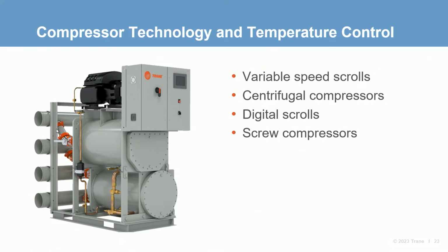As shown on this slide, a centrifugal compressor designed with an integral drive could be a great choice. Same benefits of modular, very efficient, oil-free, and offered with shell and tube heat exchangers. Digital scrolls or screw compressors could be an option from some manufacturers as well.